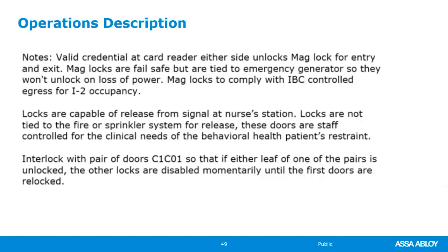Code-wise, here's our operations narrative. Valid credential at card reader, either side unlocks Maglock for entry and exit. Maglocks are fail-safe, but are tied to the emergency generator, so they won't unlock on loss of power. That itself is an exception if it's behavioral health.